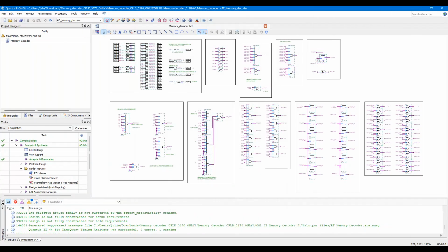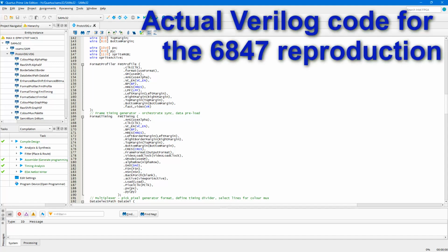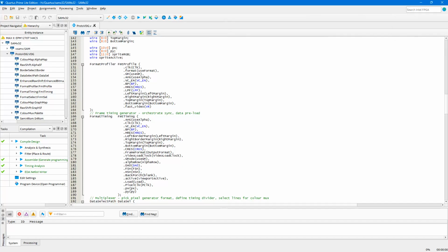Other options exist, typically centered around graphical design interfaces that allow the developer to create systems in much the same way as creating physical PCBs. No one solution wins, unfortunately. My choice is typically to use Verilog, as it allows for great control when designing virtual test benches to verify what you've coded actually behaves as intended. And this is also one of the problems with Verilog. You can design and test stuff that can't be synthesized.